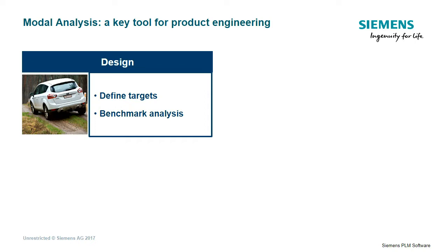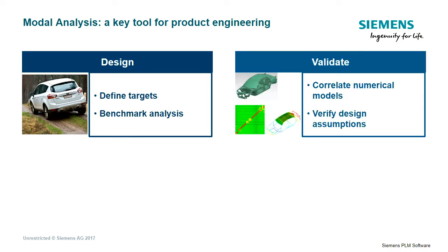Alternatively, it can be used for benchmarking and thus gaining deep insight into competitive products and provide an answer to the question, why do they perform better? Secondly, modal analysis gives you a set of objective and invariant quantities, which can be used to validate and improve numerical models, more particularly finite element models, but also to verify some design assumptions.